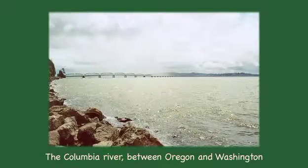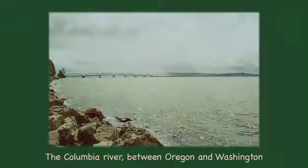Channel storage is the one-dimensional process of runoff diffusion, that is, flow attenuation, while the flow travels through the river channels. In mid-sized catchments, depending on size and prevailing slope, runoff is controlled by both overland flow and channel storage.